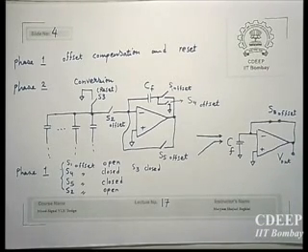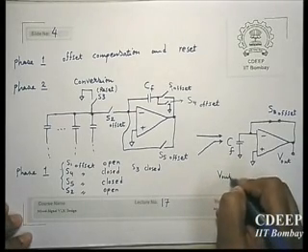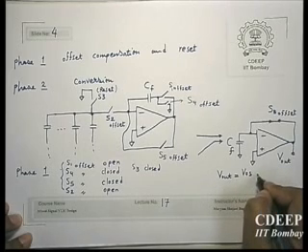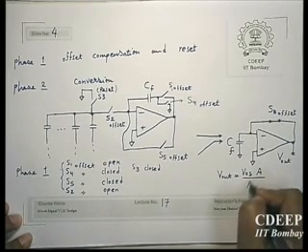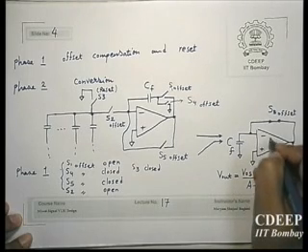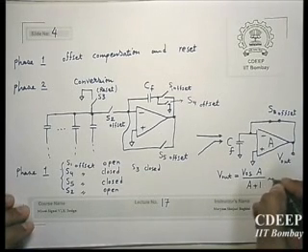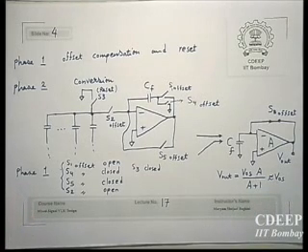Okay, so because it is in unity gain feedback, we saw before the output was V offset times (A plus 1), right? This op-amp has gain of A. A is positive. So if A is large enough, this can be almost V offset. So we need to have a high enough gain op-amp so that the error we get here should not be more than half LSB.